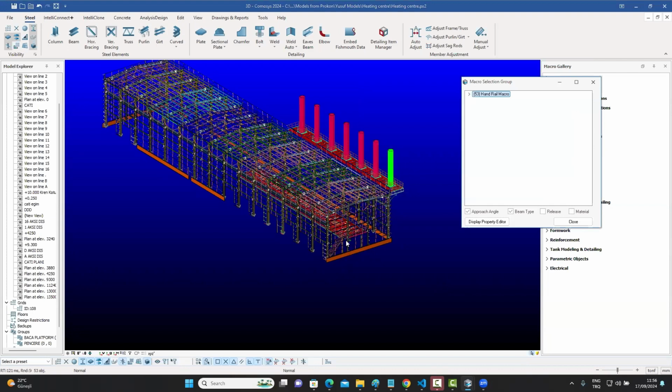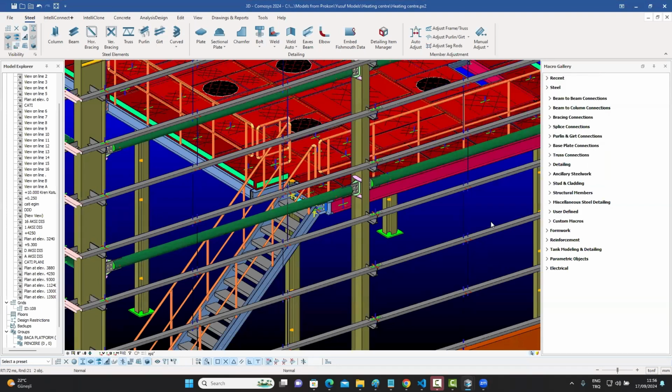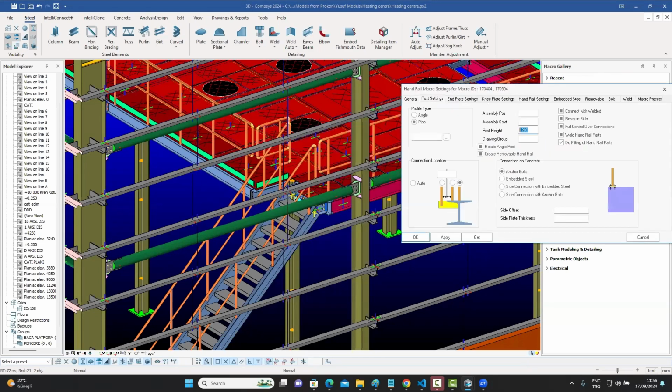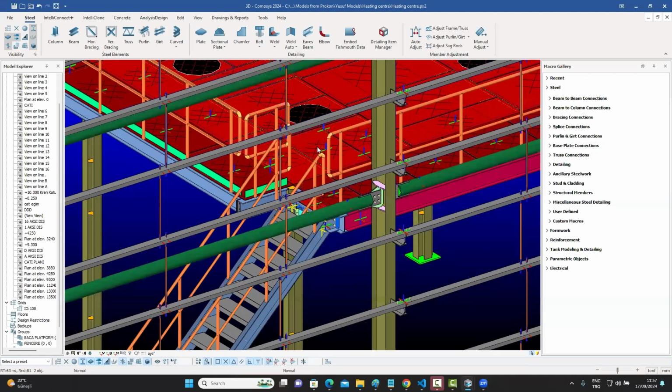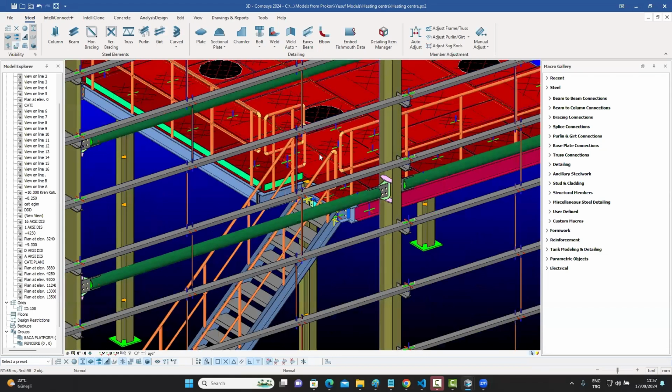And this time, instead of opening up the entire lot, I know this is the one I want, the UNP ones with the main being UNP 200. Okay, there are only two, but they could have been 200. And I just go back into the dialog box and I say, okay, this one doesn't need to be 1200, it needs to stay at 1000. And I press OK, and you will see on the screen how this will change, right? So those, basically, however many there were, they have now been brought back to the level.